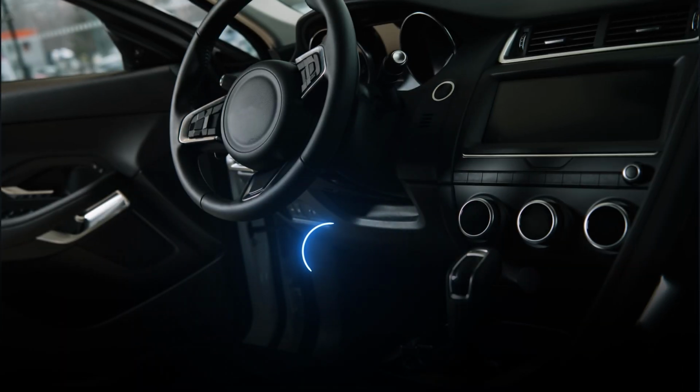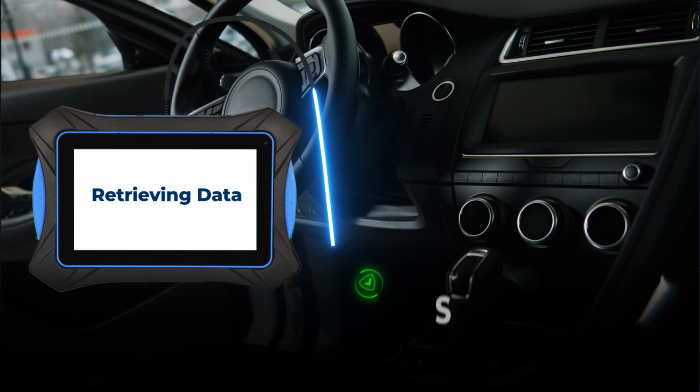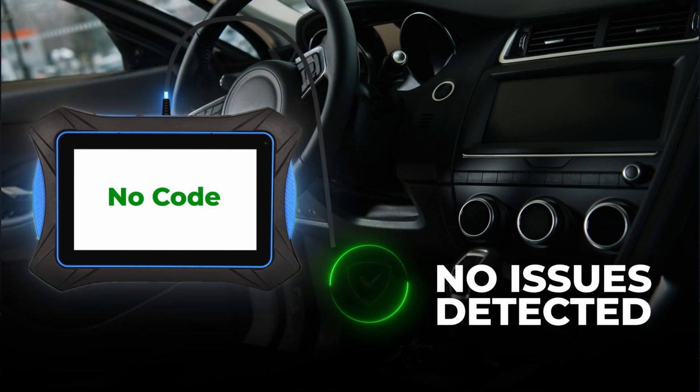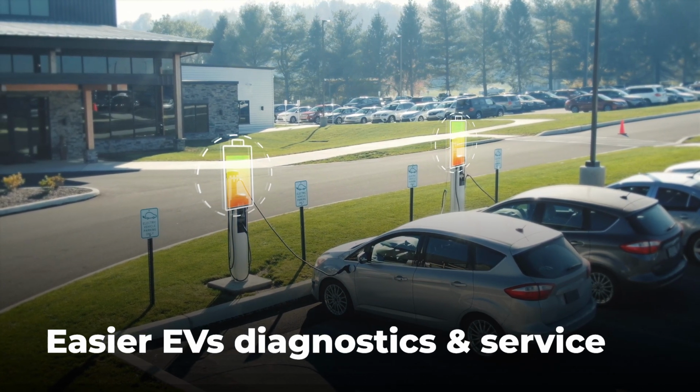To perform diagnostics, just follow the usual procedure. Plug the scan tool into the vehicle's DLC. For vehicles with new EV standard support, the tool enables system data retrieval, detects fault codes, and checks the health of other EV components. This new standard helps automakers design electric vehicles that are easier to diagnose and service.